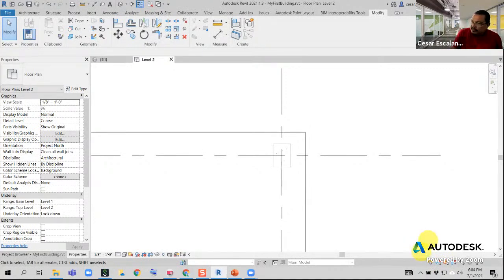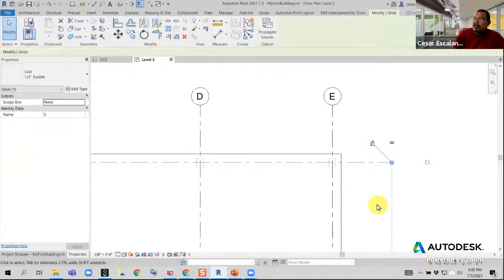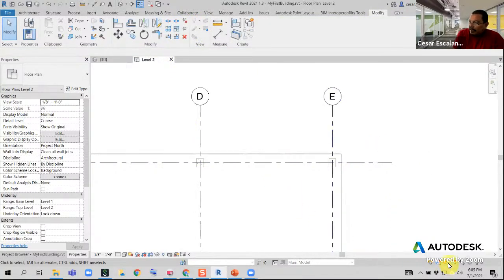So these are the selection controls, if you remember the name. I think we look at a couple of them. These enable or disable the user's ability to select pinned objects. Remember, if I select a grid and then I pin it, and I disable the ability to select pinned objects, then this grid is a reference. You cannot select it, you cannot move it. And maybe that's a good thing. Maybe pinned objects are there so that you don't select them and you don't have to move them.